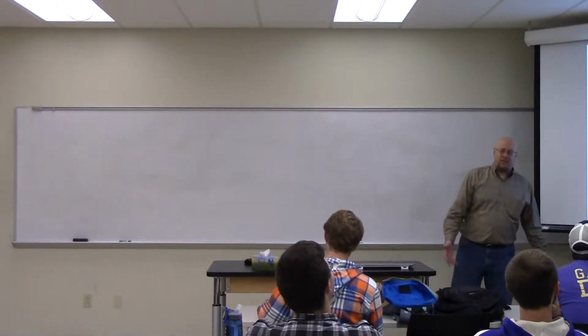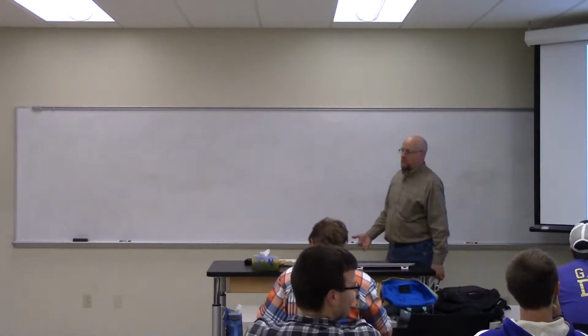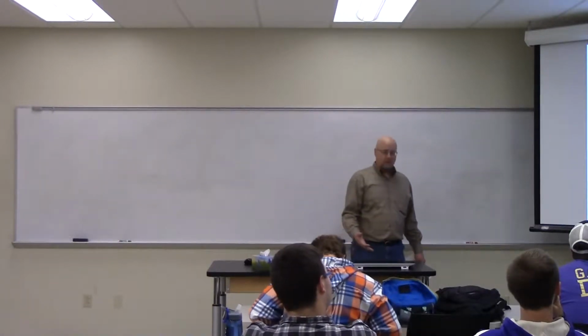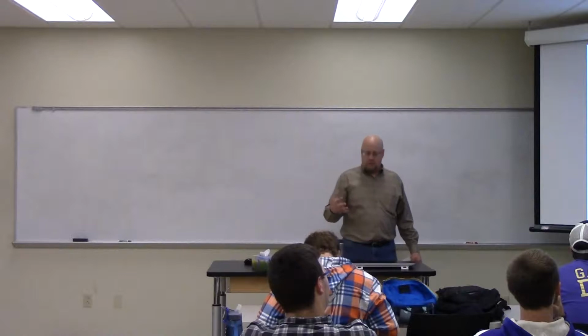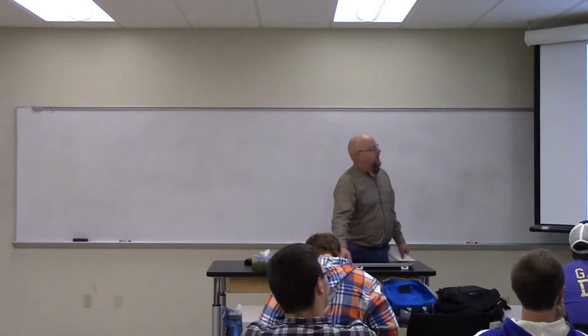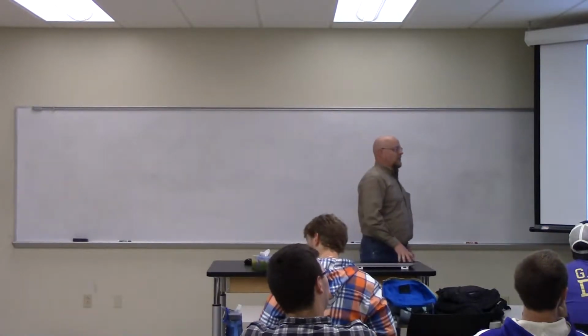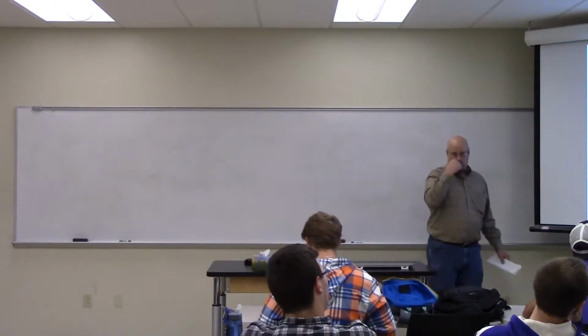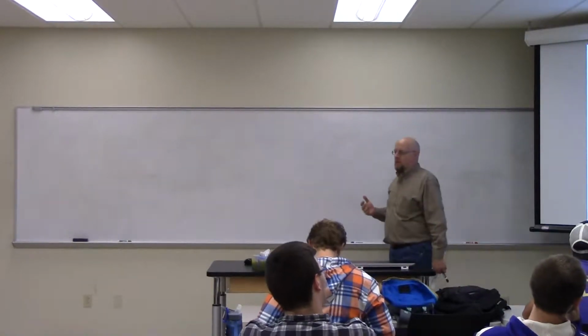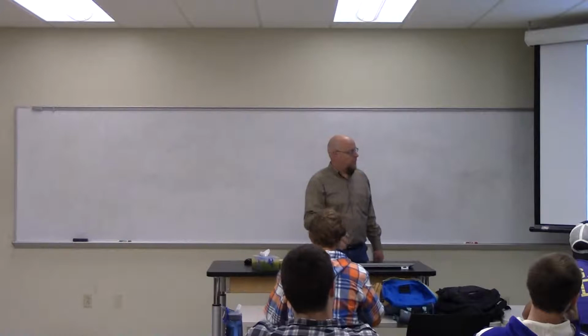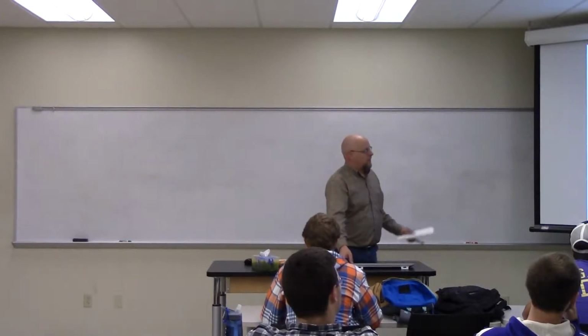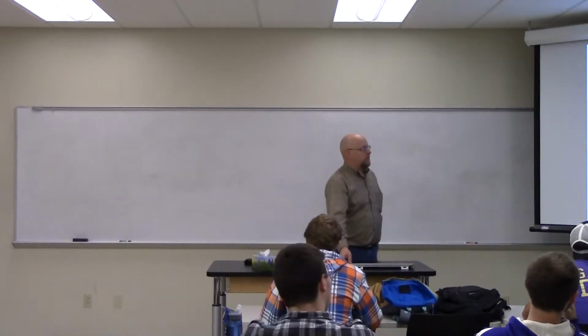So for FCC, for instance, we have this slip system. This is one of the close-packed planes. Just wanted to make sure everybody had the concept, so I'm going back over. And then there are 3 directions in that plane, basically along the edges of that triangle. So there's 3 slip systems there.